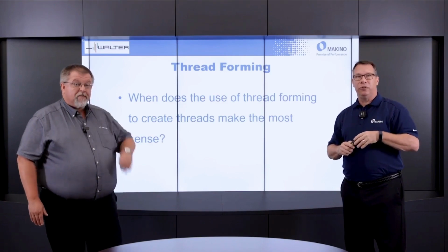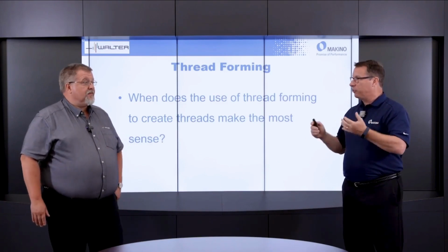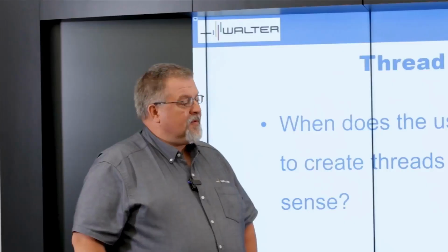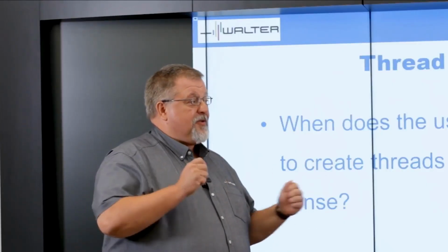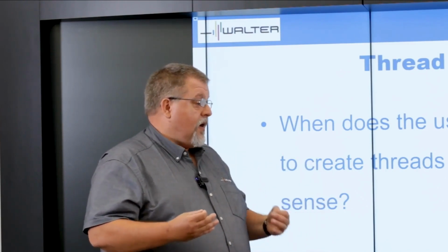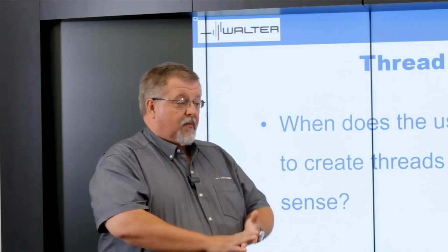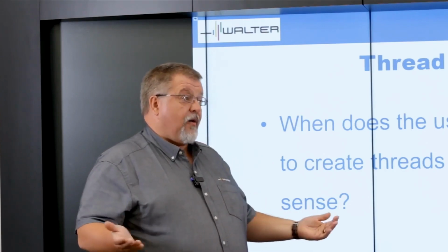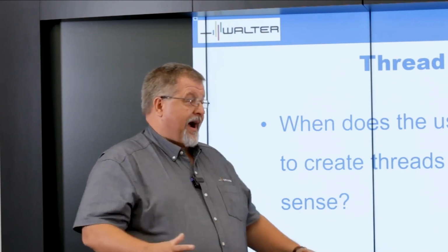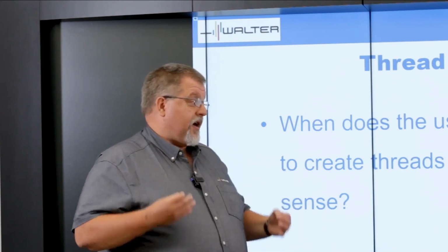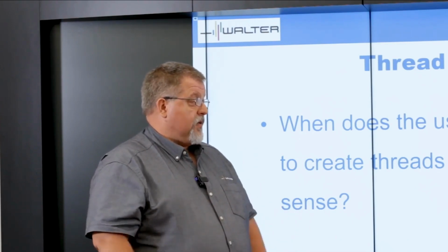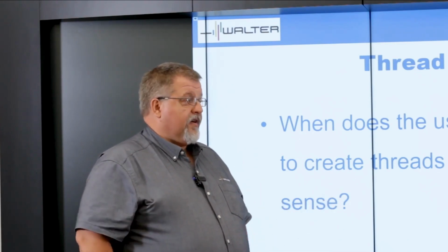Brian, when does the use of thread forming make the most sense? If somebody's evaluating what process they are going to use to make this part? Well, you said the key word earlier, and that's on some of these automotive parts. That's where I see thread forming being the most applicable. High volume parts, a lot of the steels, the cast steels, and now the aluminums that are coming out in that automotive industry. When you're doing a high volume of threads and your cycle time is really dependent, thread forming is an excellent method of doing that. The cost per thread is very low.